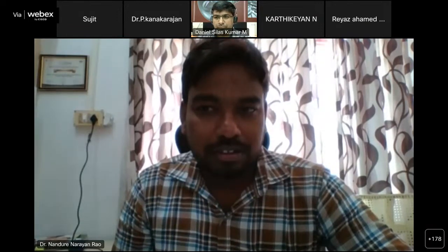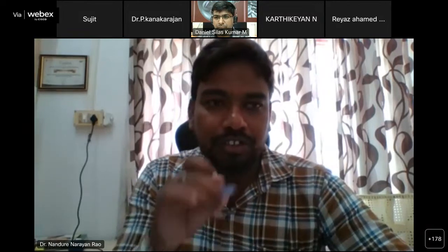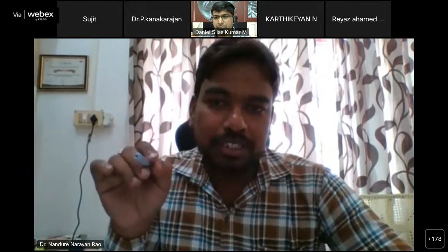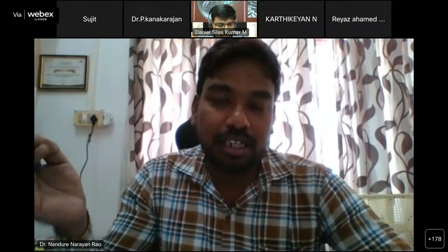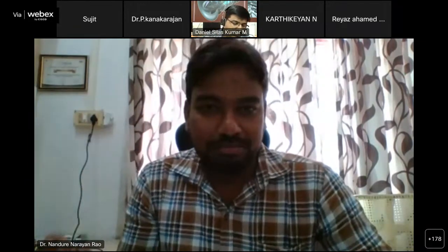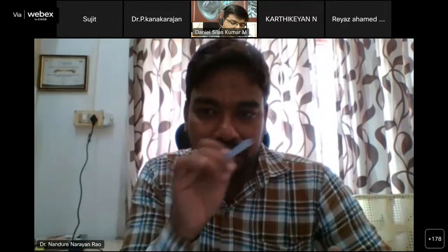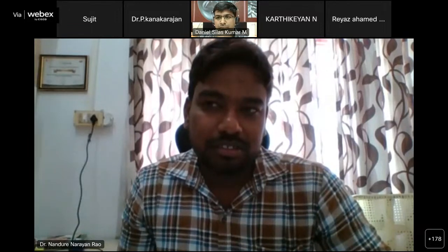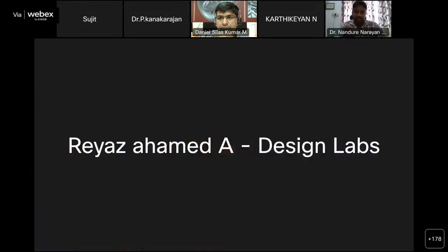Yes, the temperature changes, definitely, because you have defined a uniform temperature. If you see your results, the whole pipe is at the maximum higher temperature. Okay, it's fine, but the inlet temperature and outlet temperature should be different. Of course. But you have defined the uniform temperature across it, and you defined the inside temperature.